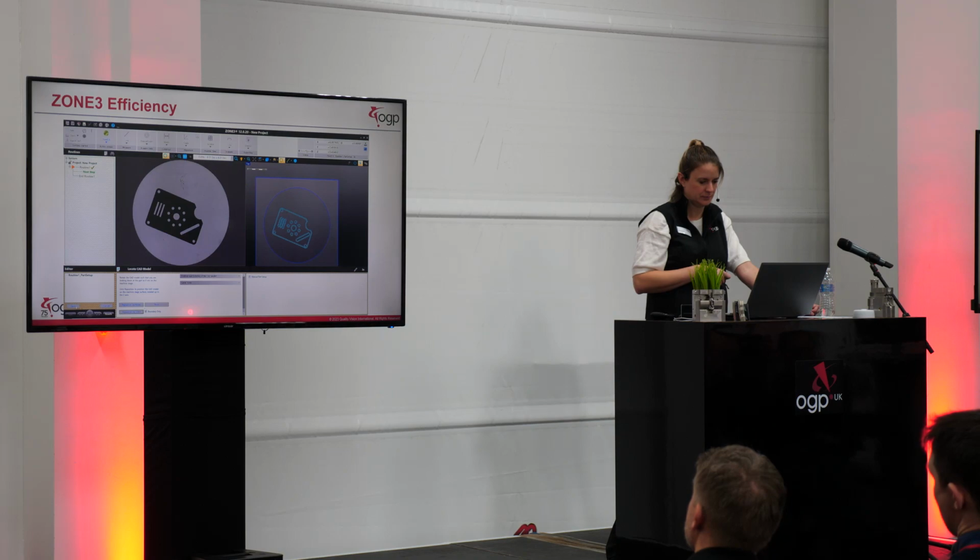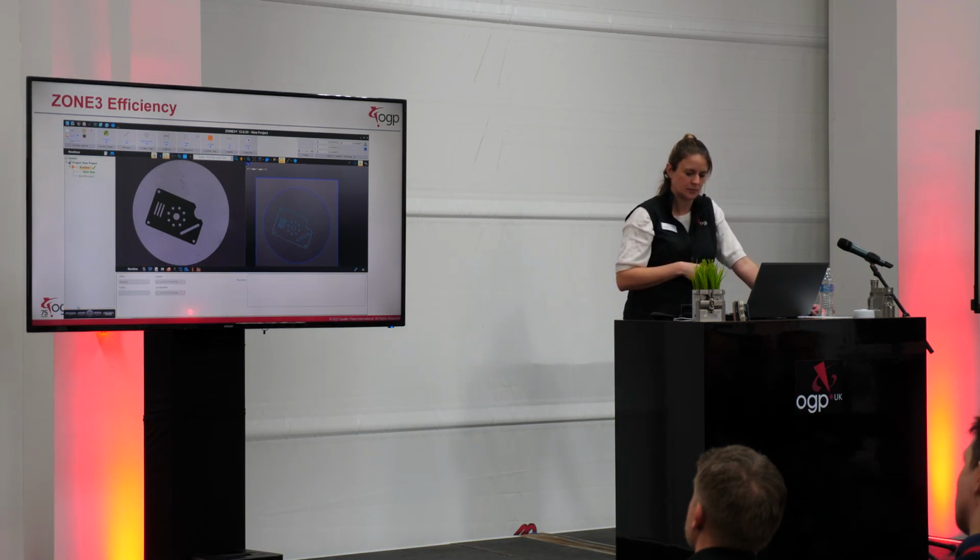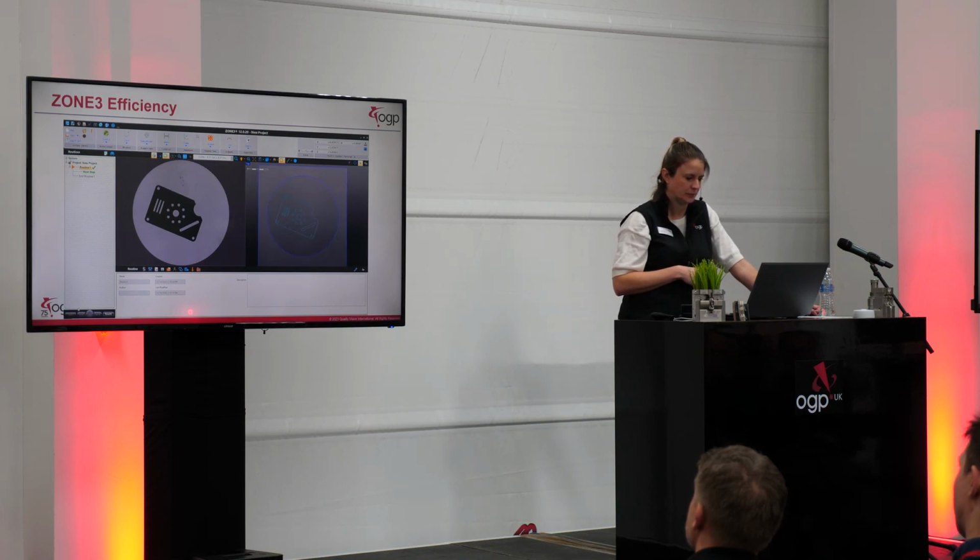This allows you to immediately begin programming off the CAD model without any setup needed. Now that my 2D CAD model is aligned to the part, I can select the Generate Steps button from the Getting Started group to automatically generate features based on the CAD model.